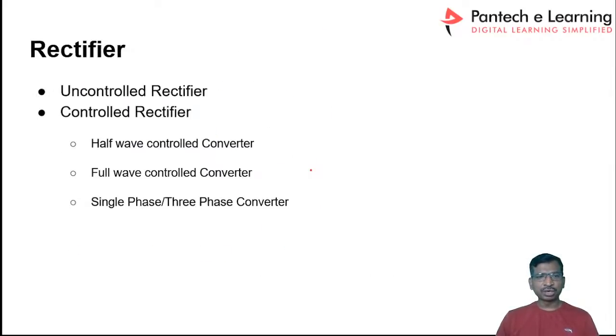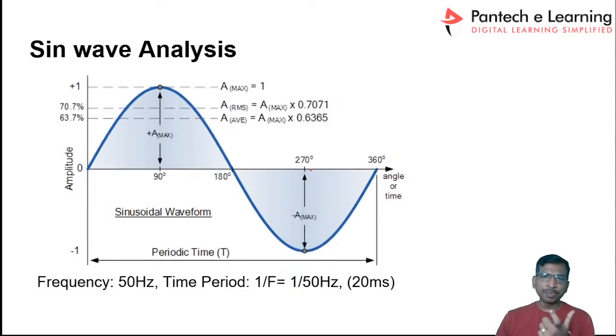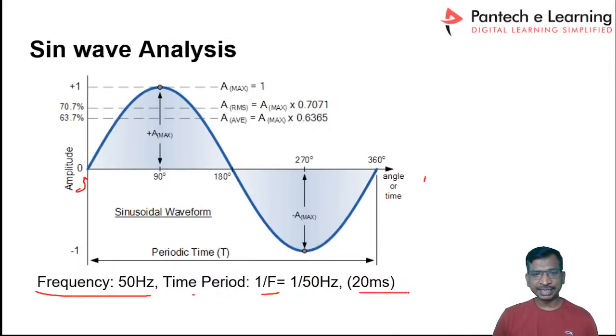So before you understand the working principle of power electronic concepts, you must know waveform analysis. If you take a sine wave, see here the entire period. This is the starting point and this is the end. From start to end, the entire period, if you take 50 hertz as the frequency, then the time period is 1 by f, which is 20 milliseconds.